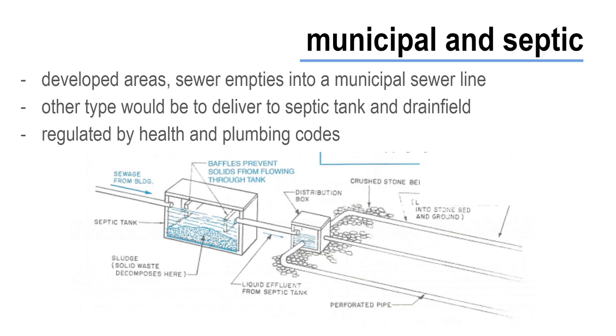So building codes will often require a percolation test before the system can get approved. In a percolation test, holes are dug and then the amount of water poured into each hole is measured, and the amount of time required for the water to drain into the soil indicates how well the soil will accept water from the septic system. This ability to accept it is called percolation. And the location of key elements in the system are often shown in the plan.